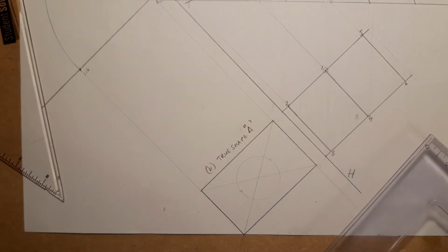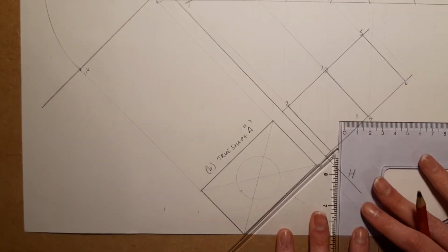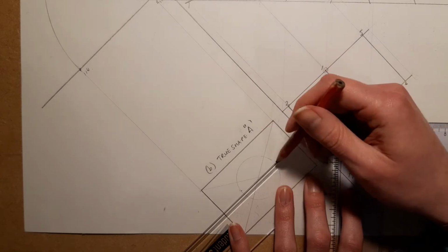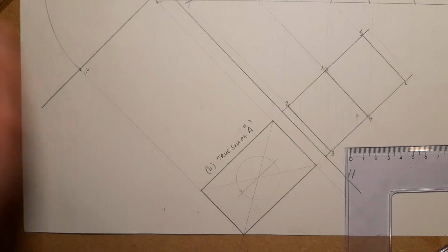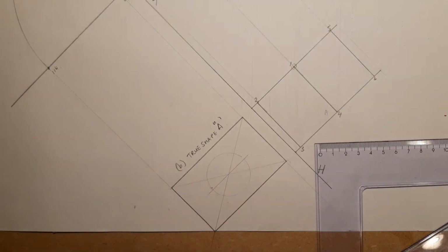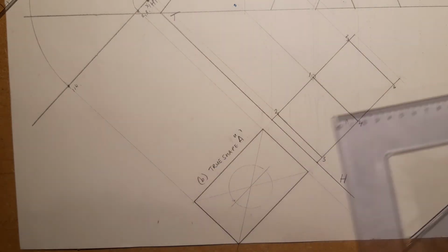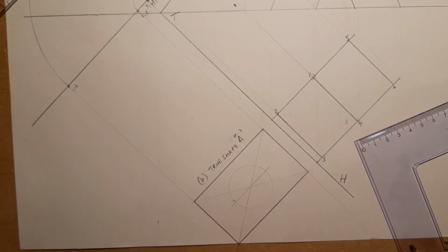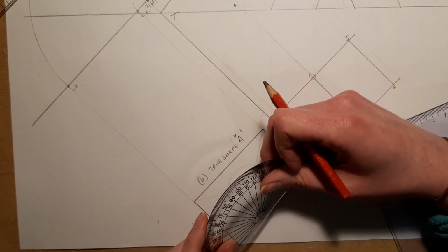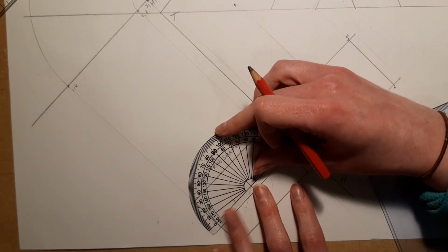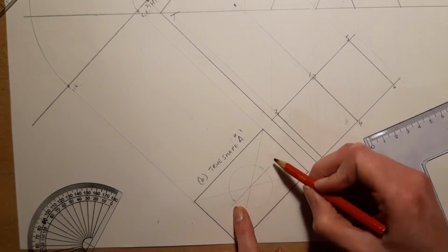So with that in mind, I'm going to ensure that the pentagon that I'm going to draw has the apex at the top there. And to ensure that, I'm just going to draw a centre line through the centre. I'm going to grab my protractor, if you have your protractor. If you don't have your protractor, you can do your set square. Slide your 30-60 set square and create a different shape instead. Now, I have to measure. 72 degrees, yeah. I can just do the 72 degrees on the inside. So put your protractor on the centre line just as it is here.